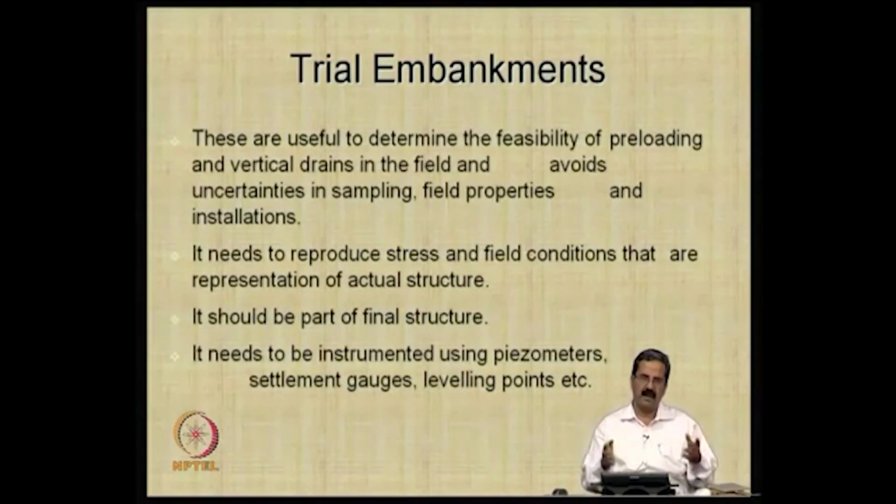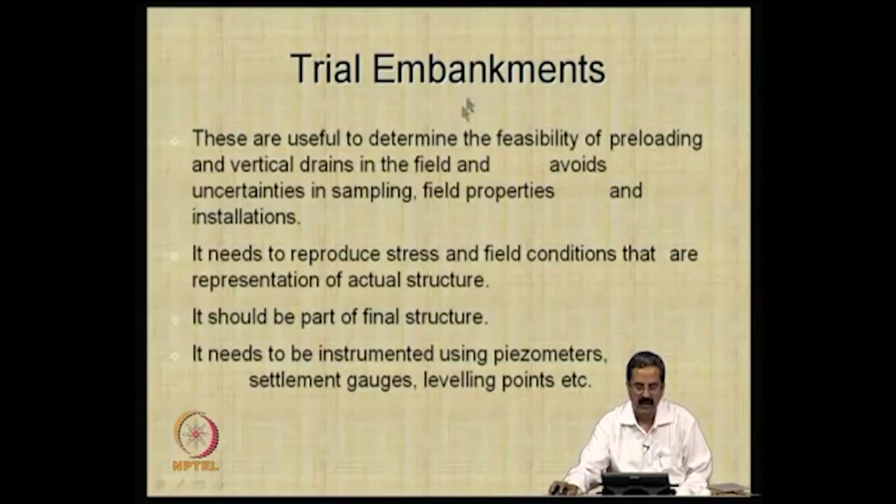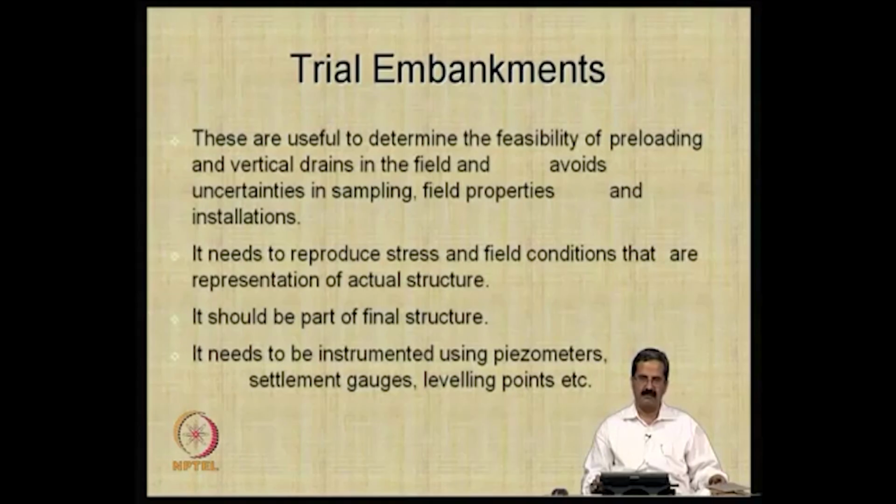The best way is to construct an embankment itself, like 5 meters height or 3 meters height or whatever height you want. And the advantage is that if you have that type of thing, it avoids the uncertainties that you have with reference to sampling, and other difficulties like installation.